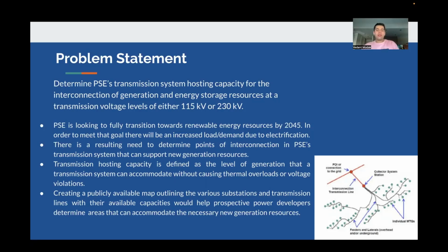Thus, there's a resulting need for us to determine points of interconnection in the transmission system that can now support these new generation resources. For anyone who's not from an electrical engineering background, system hosting capacity can be defined as the level of generation that a transmission system can accommodate without causing thermal overload or voltage violations.